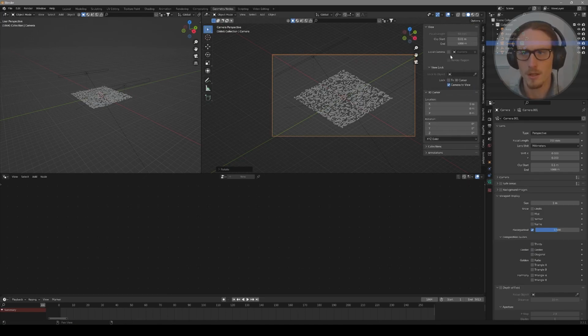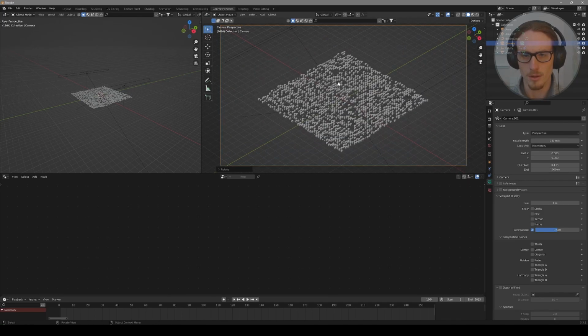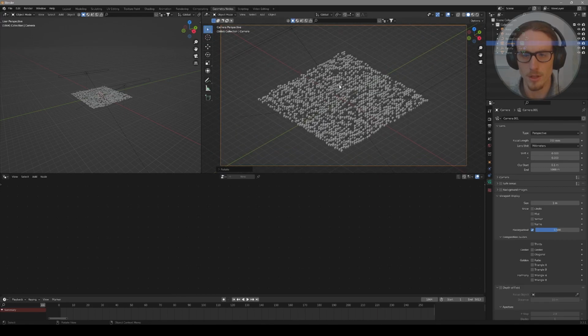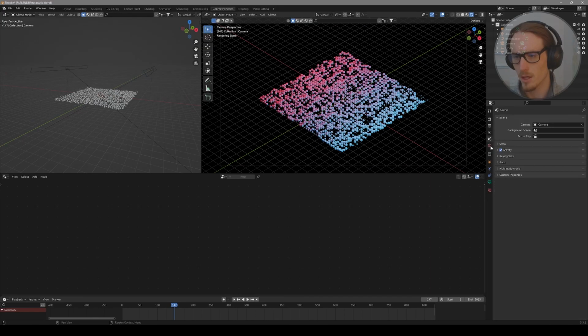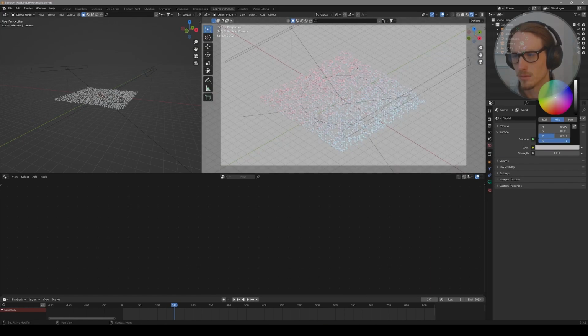And then I'll press N on the keyboard to uncheck Camera to View so that I can leave the camera in that location. Now when I zoom in and out, I'm not affecting the location of the camera, I'm just zooming in on the photo that I'll be rendering. If you want to change the overall background of your scene, you can go to your world properties and change the color. I've got mine at black.